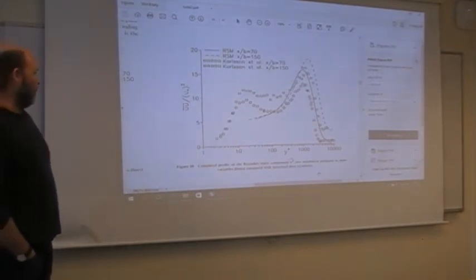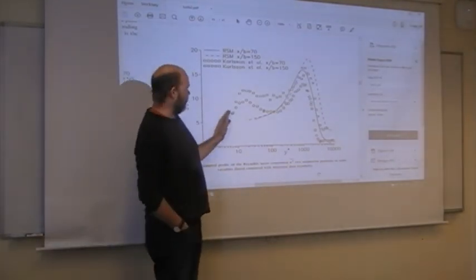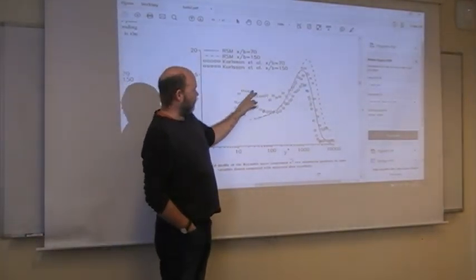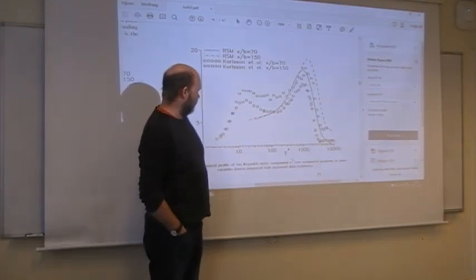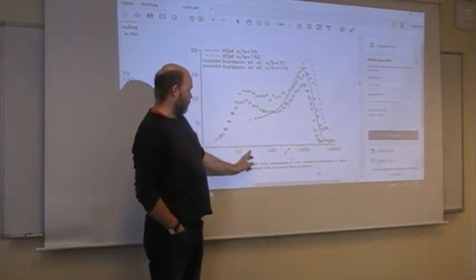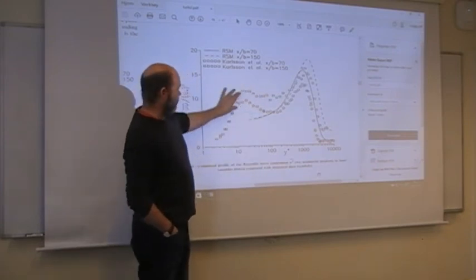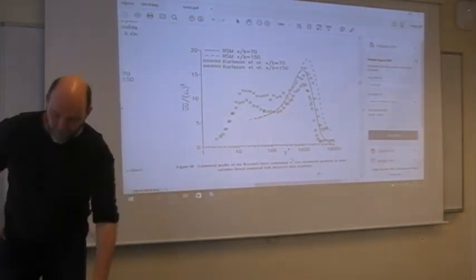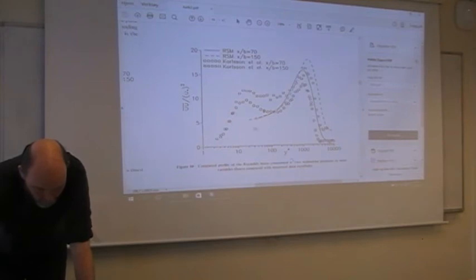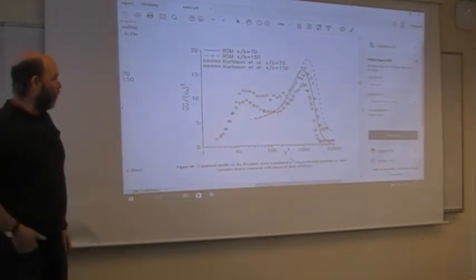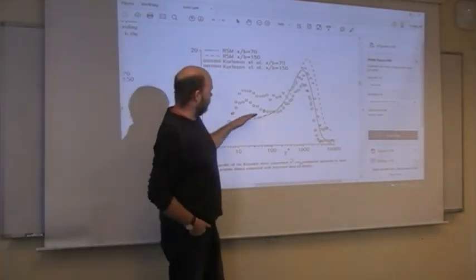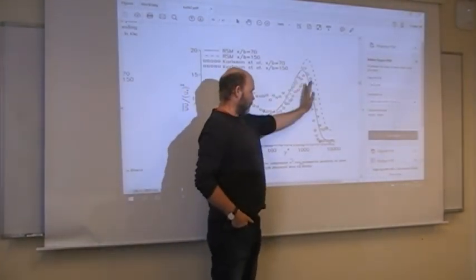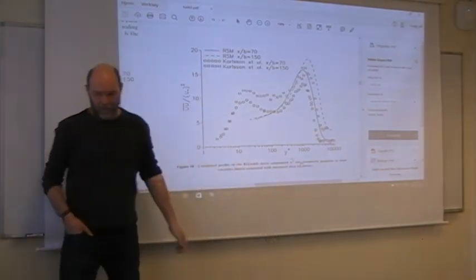It's getting very tricky to get the experimental data to get this behavior correctly. Remember, the simulation starts at the first grid point. So of course you can't mimic all this physical behavior very close to the wall. The wall model will smear everything out. So what you can hope for is a decent result in the outer region, outside the inner layers.